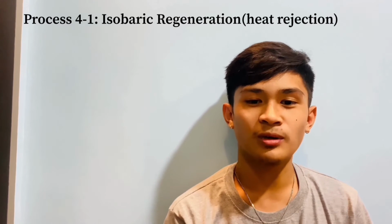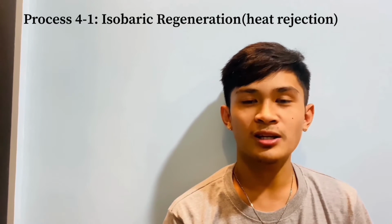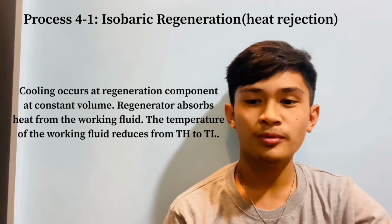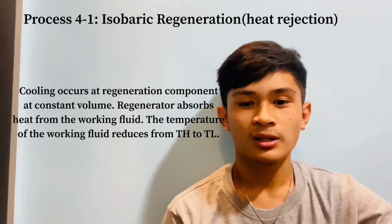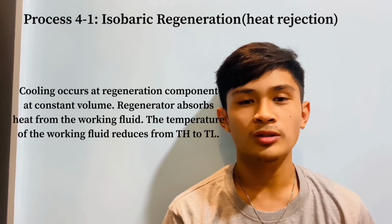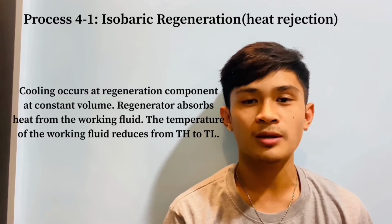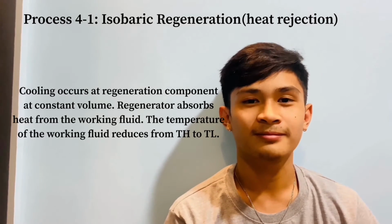Process 4 to 1, isochoric regeneration, heat rejection. Cooling occurs at the regenerator at constant volume. The regenerator absorbs heat from the working fluid. The temperature of the working fluid reduces from T sub H to T sub L.